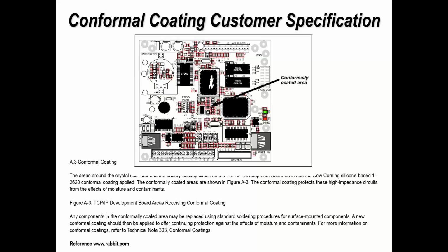So in terms of conformal coating, whatever material or process you use, it's important that the design engineer or the quality engineer define what material you want, what that actually gives you in terms of material and performance, but also you want to define where you want it and where you don't want it. So normally speaking, when I talk about inspection criteria, you also got to have something which says, I must have it there, I don't want it there, and it doesn't matter if it's here. Now that might sound a bit random, but sometimes, depending on the process you use, you can get overspray.